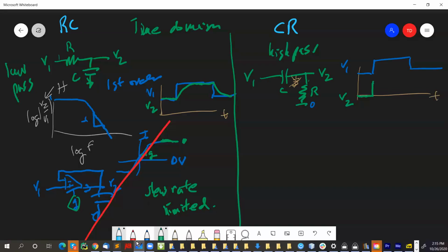And now what happens? Now suddenly the voltage is high. You suddenly dump some charge Q onto here through this capacitor, and it's raised the voltage V2 up high. Now this charge Q leaks away through the resistor, but with the same exponential behavior exactly as for the RC low pass, right? It'll leak back to 0, with some time constant tau.